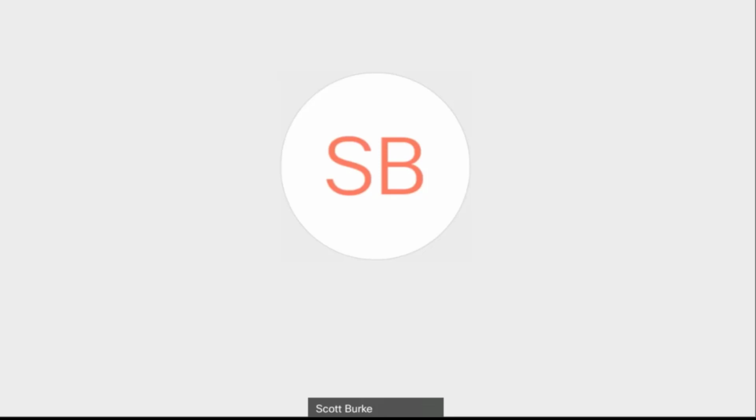So another question here, can you link a file from your server to a Revit file living on the BIM 360 design? You can do that, and as long as everyone who's accessing the file in the cloud is in your office and has access to that location, the link will work. But if you sent that file to someone outside of your company, or you were not in the office when you tried to access the model, you would not have access to that linked Revit file. So that's going to be the only issue, especially in this situation where everyone's working from home. You really don't want to be doing that. You really want to be keeping everything in the cloud.